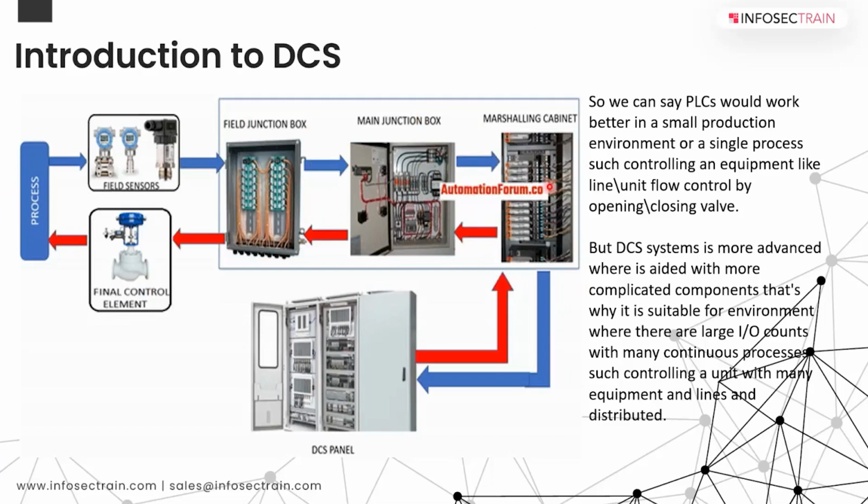The reason we have it is purely best practice. If it's a small plant it's okay, but if it's a huge plant you'll have thousands and thousands of wires of different configurations coming in, and it'll be a mess to connect directly. So this is good practice, and any troubleshooting or maintenance will be much easier to do. Basically the DCS will collect all the data from the field, and it will utilize this data to control the specific process.